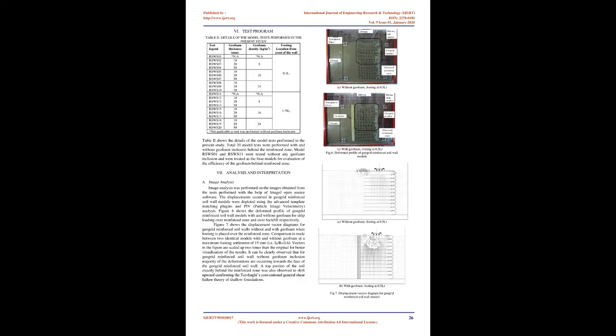At the same time, the elastic modulus was observed to be 850, 2100, and 3700 kPa for geofoam F1, F2 and F3 respectively. Figure 4 shows the uniaxial unconfined compressive stress-strain variation for the model geofoam used in the present study. Properties of the model geofoam are summarized in Table 1. Fig 4. Unconfined uniaxial stress-strain behavior of model geofoam. Table 1. Properties of the model materials used in the present study.